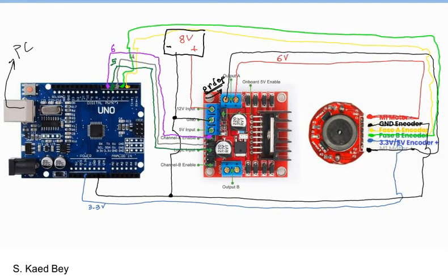It would be interesting to see the open loop performance of this hardware first, i.e. without implementing any controller in the Arduino. This can be done by, first, we can input the 200 RPM value as a user input, and inside Arduino we convert this to a voltage equivalent that will be fed to the motor driver via pin number 6.